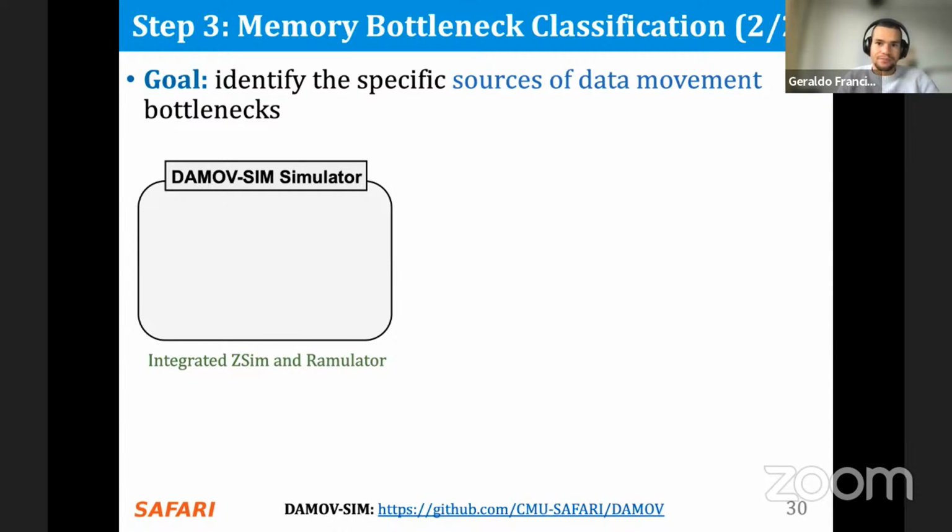To this end, we build a framework that integrates the ZSim CPU simulator with the Ramulator memory simulator to produce a fast, scalable, and cycle-accurate open-source simulator called the NDPSim. We use ZSim to simulate the core microarchitecture, cache hierarchy, coherence protocols, and prefetchers. And we use Ramulator to simulate the DRAM architecture, memory controllers, and memory accesses.